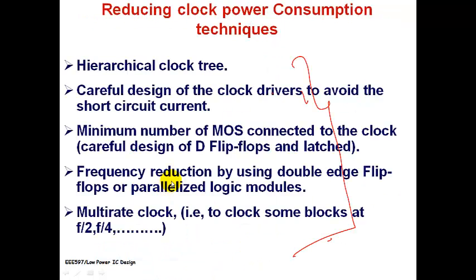So we go for a hierarchical clock tree, and to the extent possible we would want both arms to have the same clock load and the same amount of skew, using the H-tree we had been discussing in the previous slides.